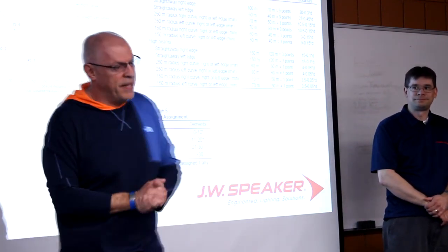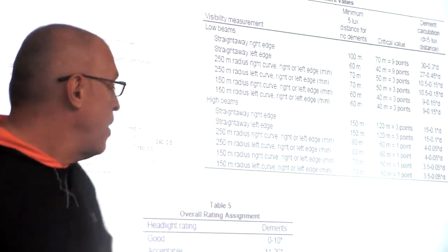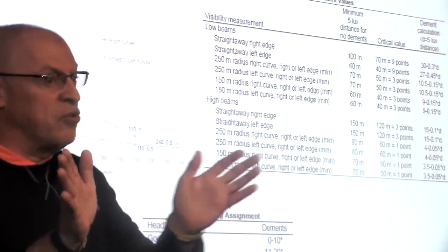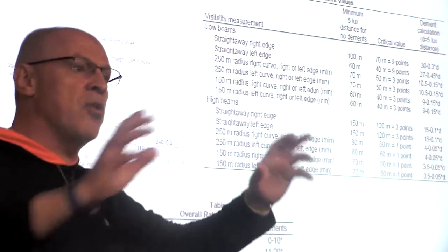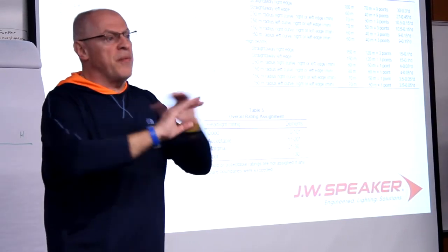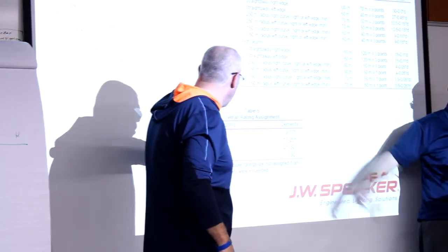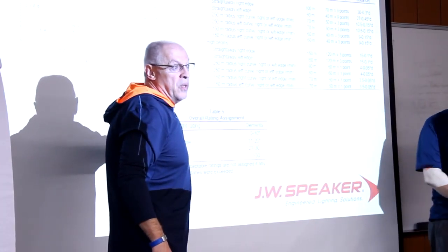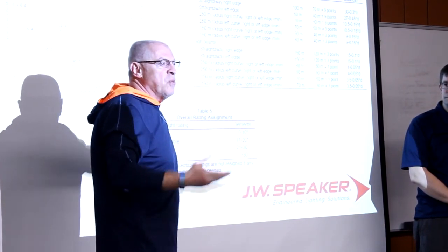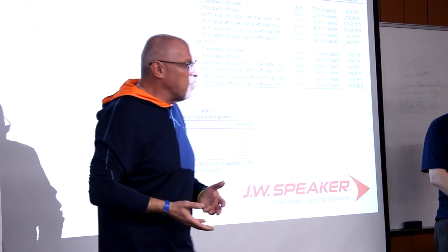Well, it's all kind of convoluted. Anyhow, there are three of them. Consumer Reports and IIHS are a little bit like this. Consumer Reports prefers more spread light and doesn't care that much about the glare. These guys care about the glare. You can be beautiful, but if you have 1 point in the glare, you're immediately marginal at best. Which means, from our optical way, your cutoff line has to be that sharp so that you never fail that. Well, when you do that, nobody likes a sharp cutoff line.